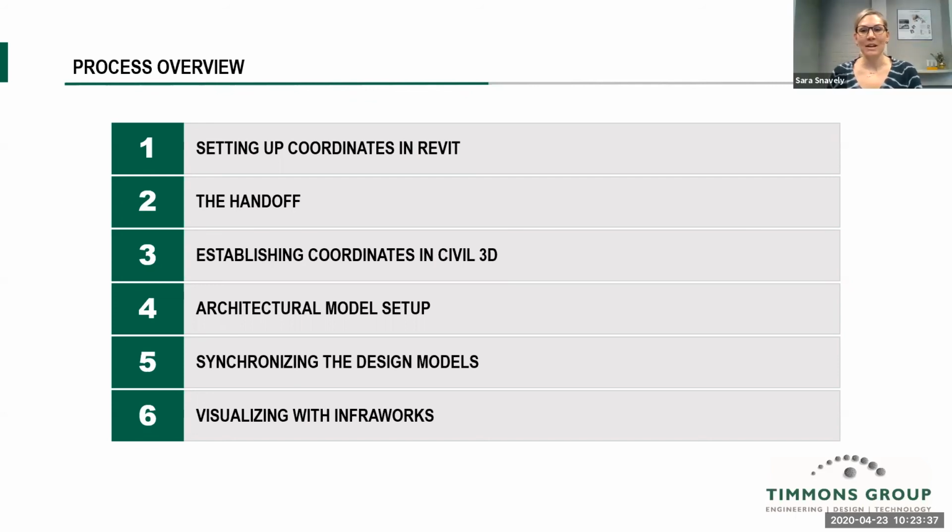Once the new site model is created in Revit and the ARC model linked correctly, can the same site model host multiple building models for phased or campus projects? So the multi-building scenario is a challenging riddle. What we're going to have is one shared reference point. If we coordinated things around one master building, we could have one civil model that ruled them all and went from there.